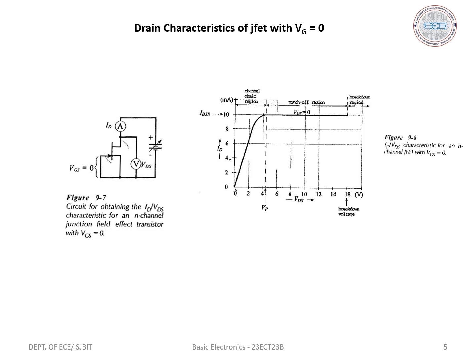Increase in VDS then has no effect on ID and it reaches a saturation level. In the graph shown above, this is the drain source saturation current, IDSS. It appears to pinch off the channel and the VDS voltage at this point is called the pinch off voltage. In this region, ID is constant and it is known as the pinch off region.